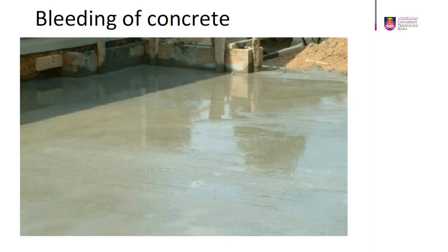The bleeding of concrete can be reduced by using finer cement, using high alkali, addition of calcium chloride, when we do concreting in a high temperature area, or when we use an admixture such as a water reducer, or an air entraining agent.